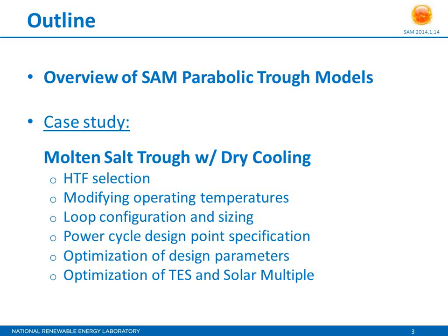We have to modify the operating temperatures to better suit the heat transfer fluid. There's some detail that we need to look at in terms of how you configure the loop, how you size the loop, how many collectors you put in the loop. And that depends on the heat transfer fluid and the operating conditions. So we'll go through that as well.